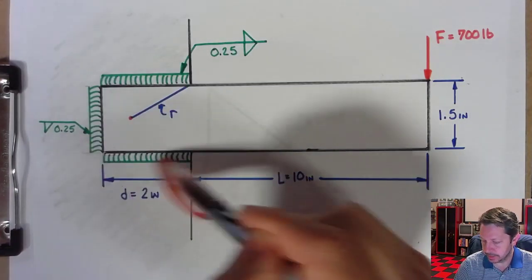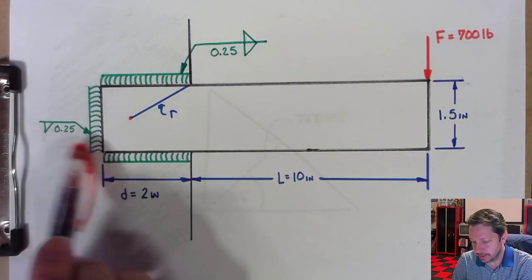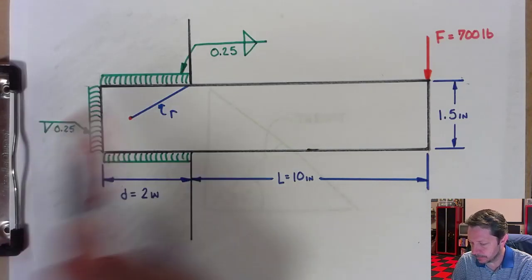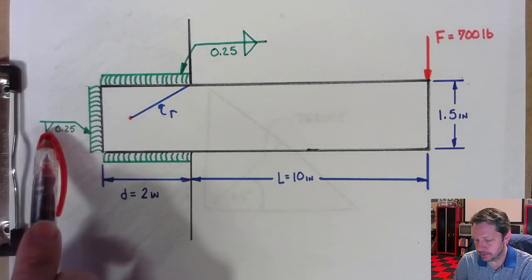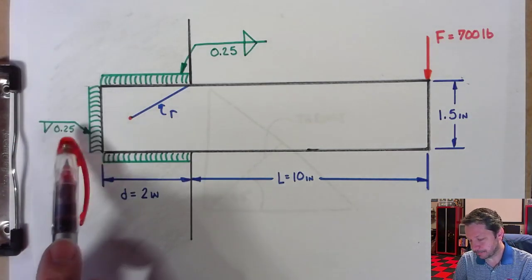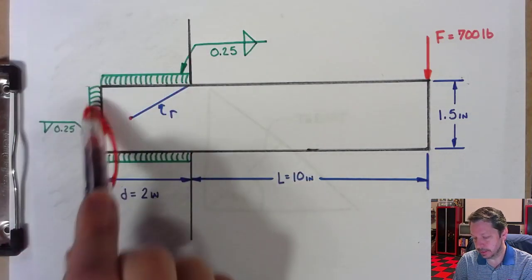I just wanted the welds on here to have a C shape. So this one has a separate call out. Now I think I do have this triangle backwards. I don't know that it matters too much, but normally they're oriented this way, so I think that it should be a mirror image, but that's not a big deal for what we're doing anyway. And it's another 1/4 inch, so they're all the same size, fillet weld, and it's only